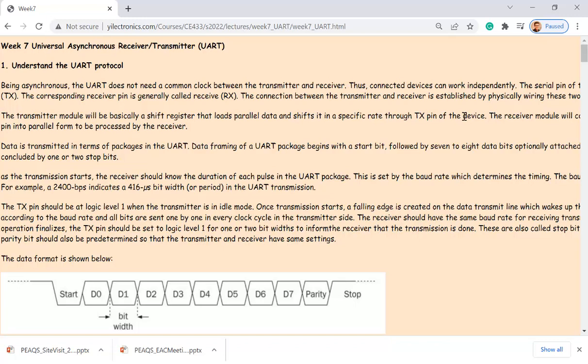It's going to blow off your Basys 3. So you need a level converter, which is a really good experiment actually. So you can learn how to use it. Grab a little module that can convert 3.3 volts to 5 volts, 5 volts to 3.3 volts. This is not damaging anyone.